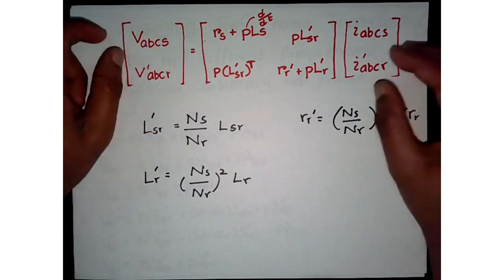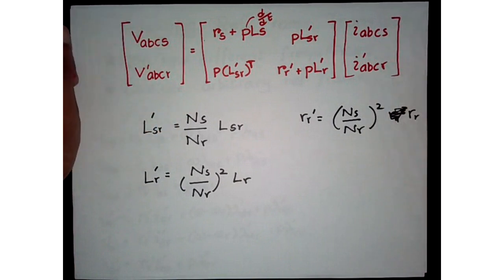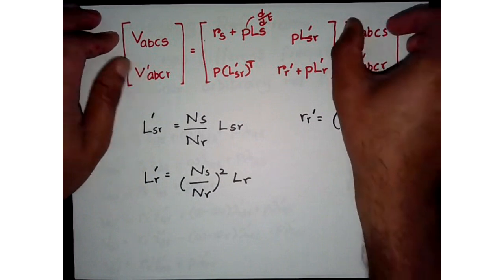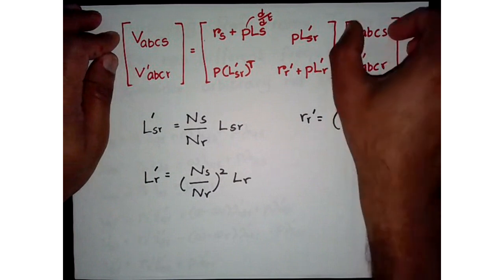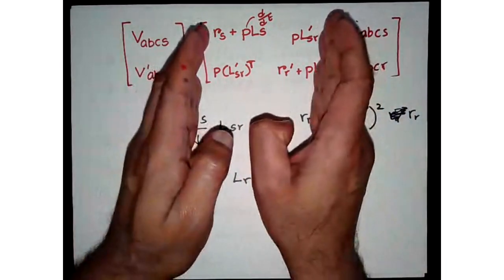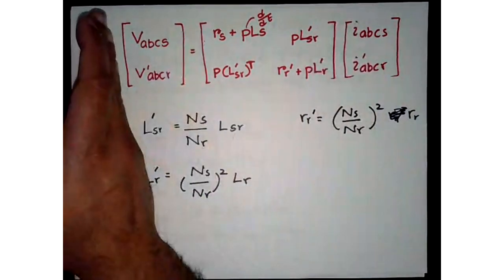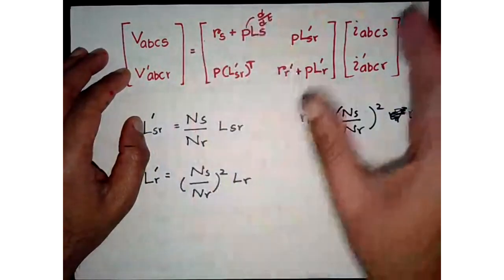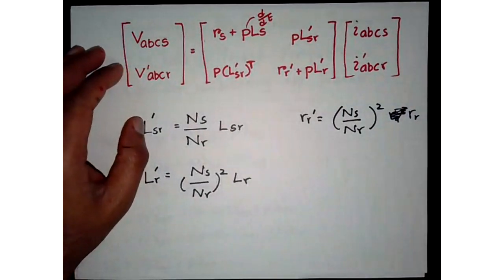For now we'll apply a fixed set of voltages, open loop, very simple control. In order to calculate the currents, we need to find the inverse of this matrix and left multiply the voltages. Okay, so that's exactly what I'm going to do here.